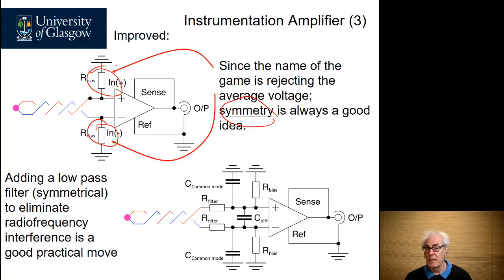If we were practically designing this, we would incorporate a low-pass filter, because temperature is not going to move very quickly, and that will filter out any of the noise that you may pick up from RF or from magnetic influences around the wiring. And that's what you would see in a real implementation of an instrumentation amplifier for practical use. I have uploaded some examples of that with particular emphasis on audio amplification, where you can see the low-pass filter designed to reject any of the RF noise at the inputs.